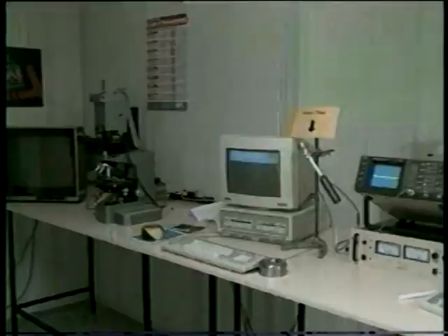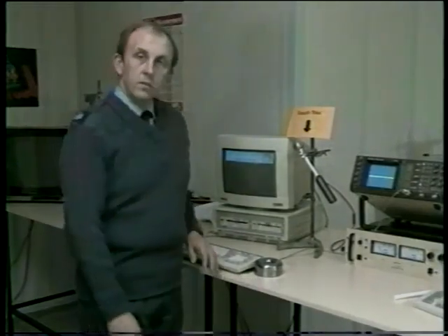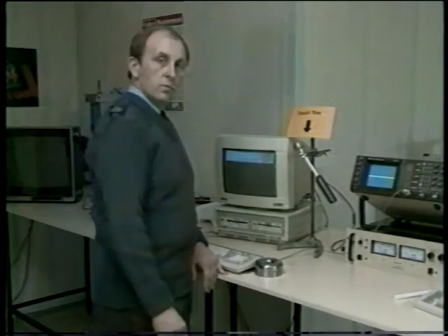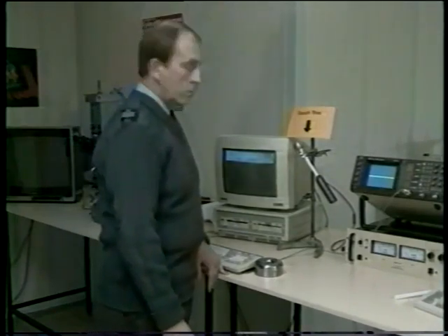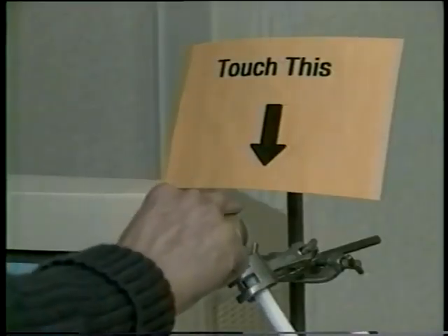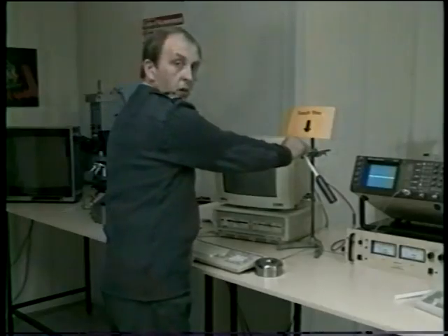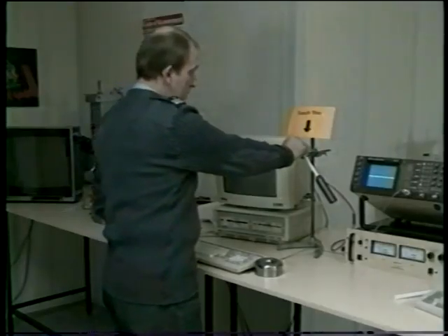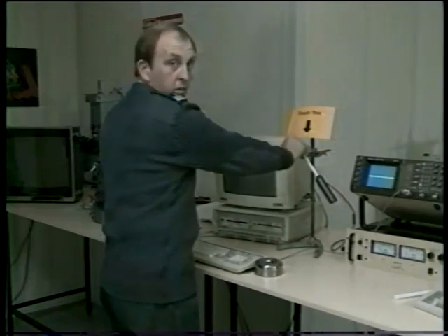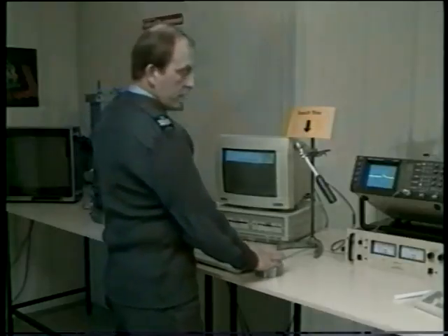Aha! The point is that you'll only feel the discharge if you're above 2 kilovolts. Devices can be affected by much lower voltages than that. I'll show you. Touch that probe. Now you're at 2 kilovolts, but you can't feel it, can you? No. Now touch this earth. No fear. You won't feel a thing. I promise. It's all right.